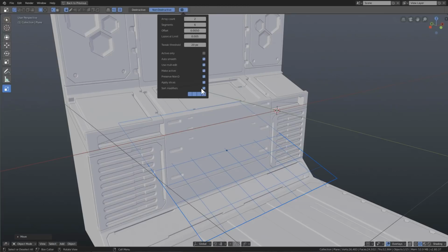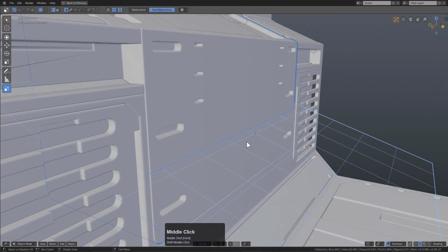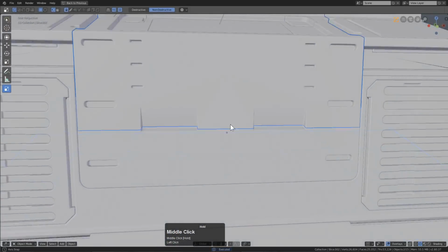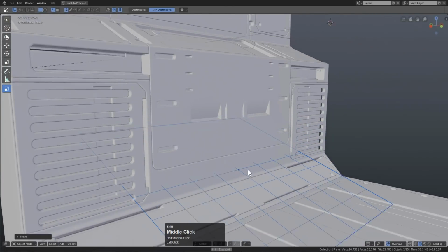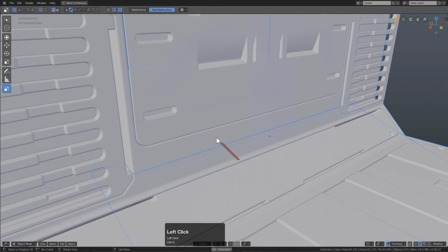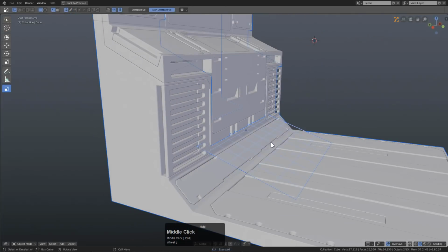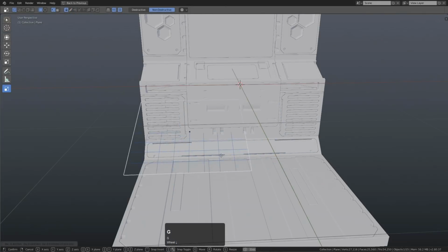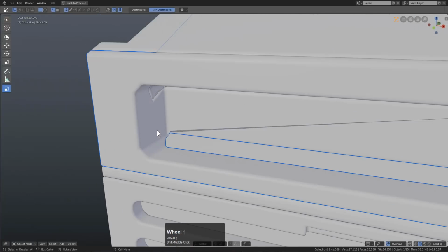I want to come up with an idea of how we can have some sort of plane-based workflow in Boxcutter. So we're going to choose active only, and for this we can now use this plane as a jump off point. And because I flipped the normals, the Boxcutter on this plane will allow me to go the opposite direction, and we can just work some little notches in here. We can select our plane, bring it down, select this. So if you're using Boxcutter and you're experimenting with this idea and you come up with some interesting thoughts and uses that could be used for helping really perfect the orientation of a box. I also experimented with using the make box, but the make box is just a box, and this is a job for a plane.